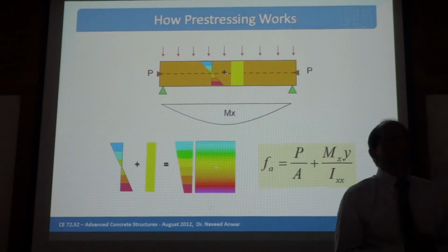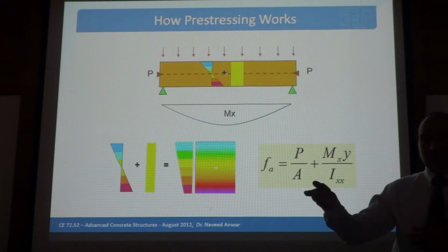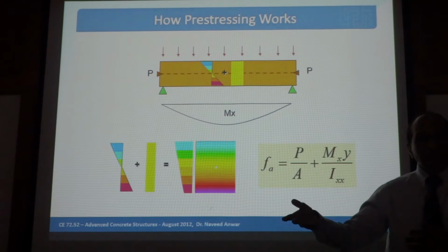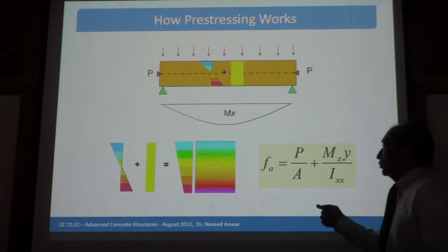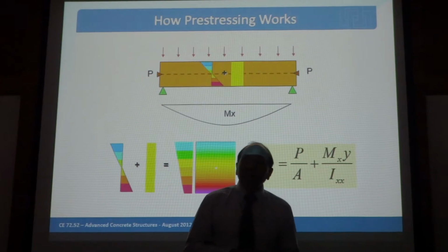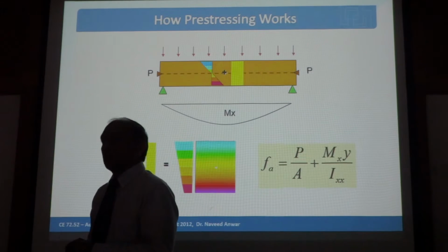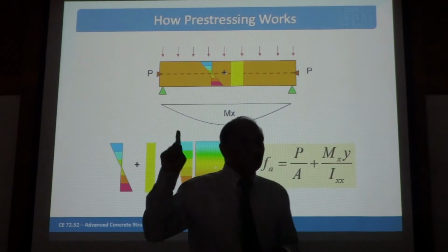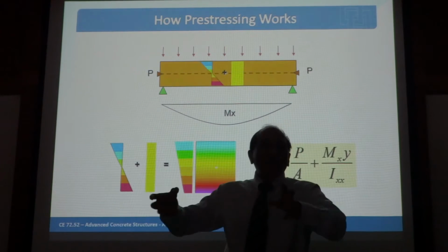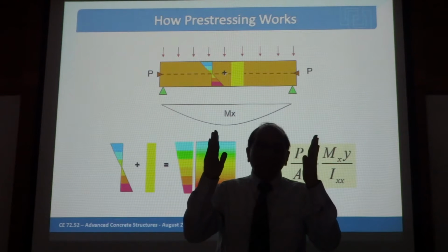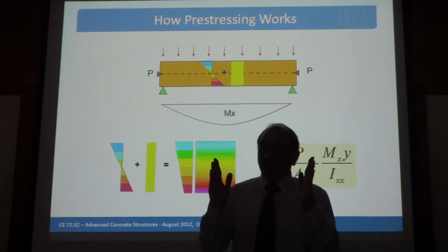And that is the whole idea, addition of stresses coming from loading and the pre-stressing. So this is the case where you put the load right in the middle, center of the section, which actually is not a very good way to go, right? It is not a very efficient way to go. So there is no load balancing, there is no negative bending, no upward, nothing. Just pure compression, balancing the stresses, right?